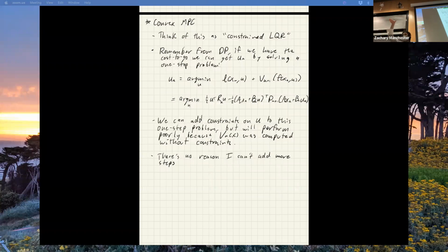And at that point, it'll back off the constraints, right? So if I have torque limits, I have a U min, U max kind of thing. If right now I'm hitting those constraints, if the system's well behaved, like 10 seconds from now, I should start to see it come down towards 0. At that point, once I'm off the constraint, then I'm back to standard LQR land with no constraints, and the cost to go is a good approximation, right? So the intuition is that if I take this horizon out longer than one time step in this dynamic programming setup, if I go far enough out before I use the cost to go, by that point, if I'm off the constraint, then the cost to go is right. Does that make sense? Cool.